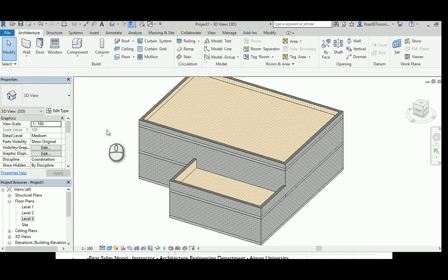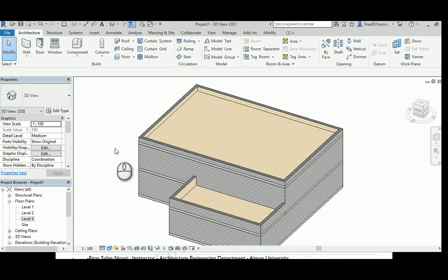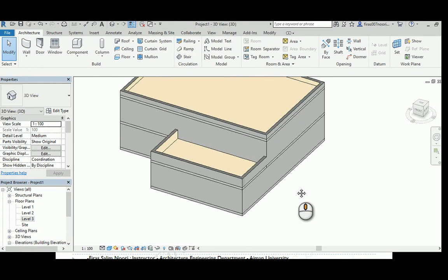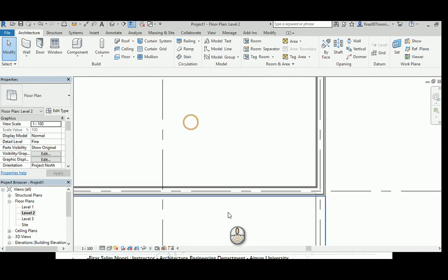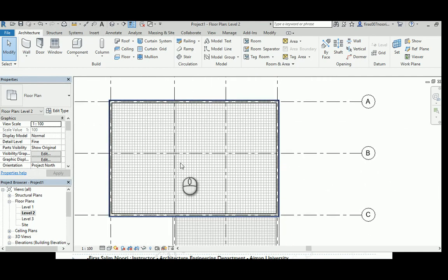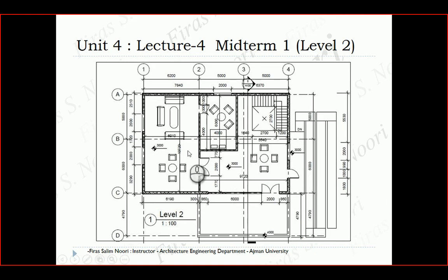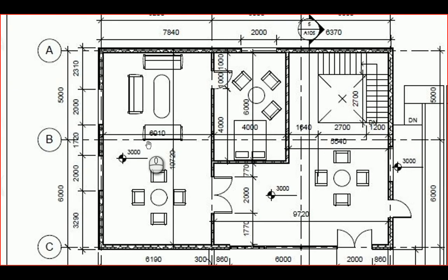Forget anything related to the doors and openings, and even the partition. Sometimes I don't bother doing them. Maybe I forgot the partition here, so for the first floor, let me do that. It's just one partition here, and then one partition here and here, based on 4,000 by another 6,000, but how much it goes away from the other wall, it's 6,010.